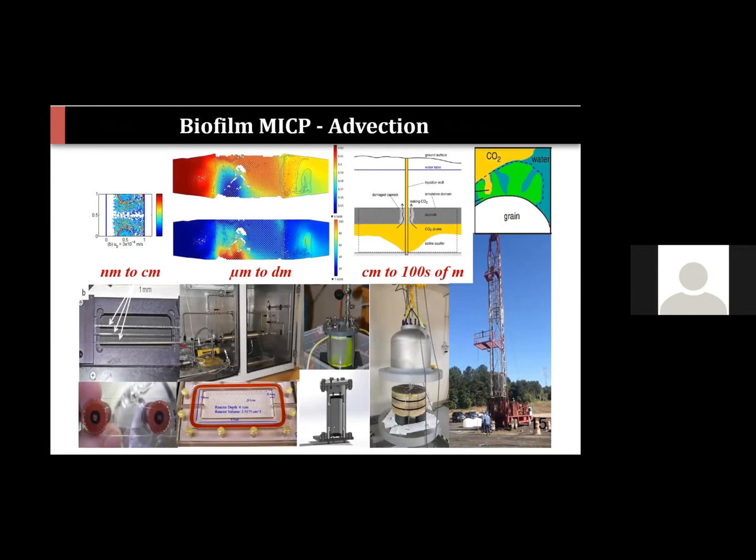However, what we wanted to do was move on from looking just at the gas solution side of things. And as I mentioned, we're really more interested in the role of the microbe-mineral interface on microbially induced carbonate precipitation for ultimately plugging leakage pathways in particular. And really, this is likely to be occurring, obviously, in natural environments under advection flow conditions. We can't just do this in simple microcosms. We have to look at this under flow conditions.